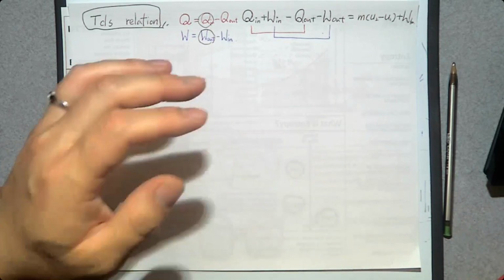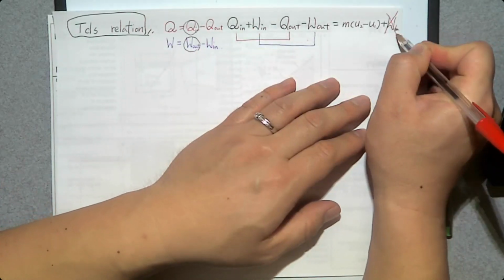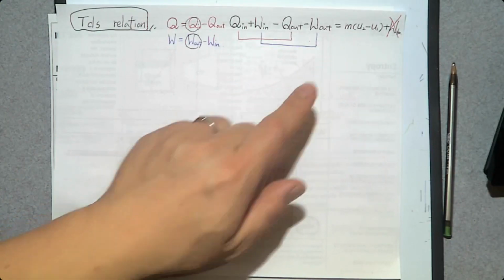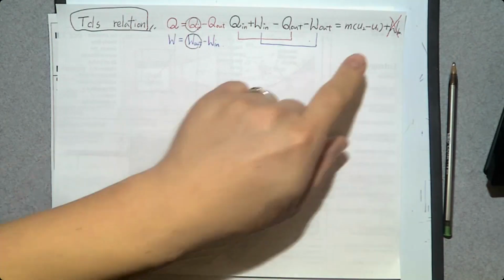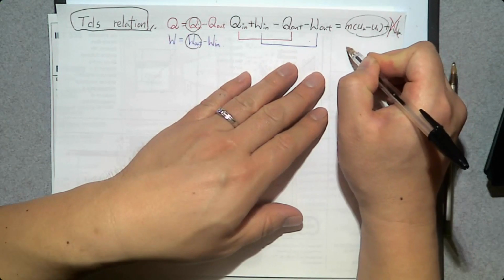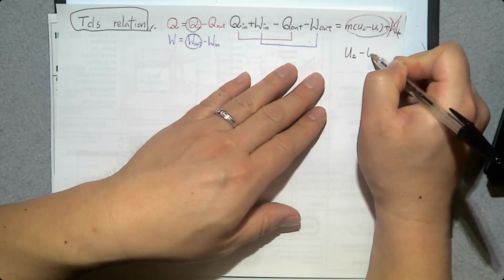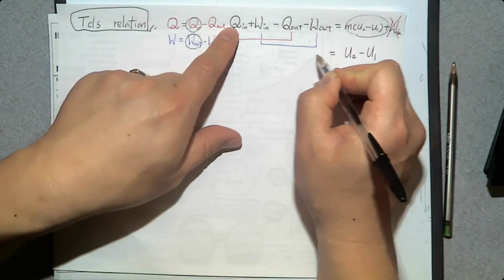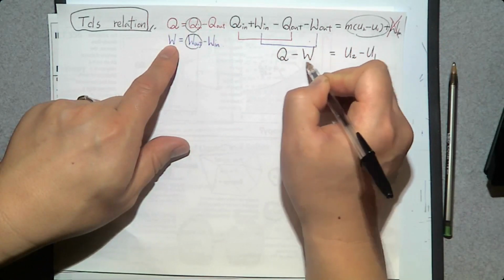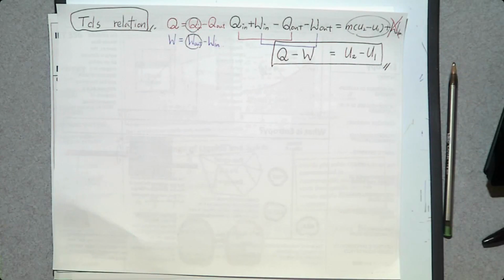Okay? And we can also simplify this one, assuming there's no moving boundary work. Then there's a mass. Oh, I don't like mass. So what do you want to do? Let's talk about that later. I can combine these two and say this big U, total internal energy, U2 minus U1, is going to be Q, net heat transfer, minus W, net energy transfer by work. So this is the energy balance equation. Okay? They are the same thing.